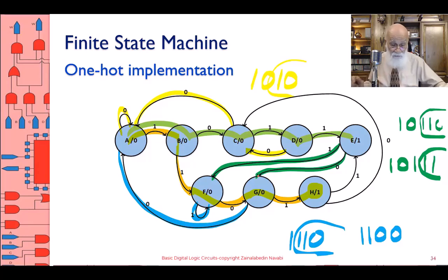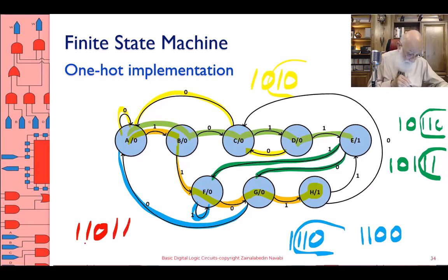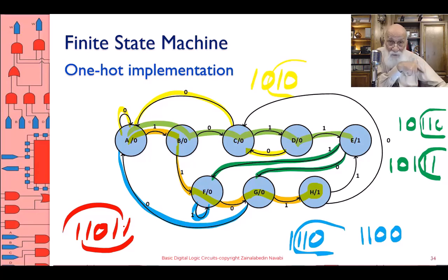Now let's look at the state H and look for the two edges out of state H. I am in state H. I have received 1 1 0 1. Another one, that's pretty good, because see, this is where I am here. I'm in state H. Another one gives me 1 0 1 1. Well, incidentally, 1 0 1 is the next sequence, and therefore I go to this state where my output becomes 1. Actually, what happens from H to E, your output remains 1.